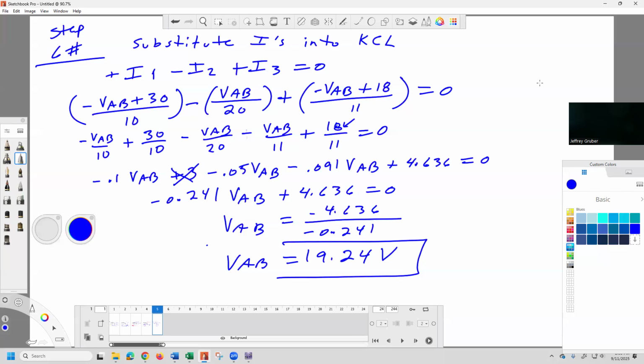So are you following? I'm trying to figure out how the two junctions, they have something between them to be two nodes, separate nodes. Yeah, because look at, if I put a meter here and measure, and then I put a meter here and measure, if there's a resistor there, those voltages will be different. If there's no resistor there, I can move my meter here, here, here, here, here, and I can move this here, here, here, here. It doesn't matter because it's a copper wire, right? I'm measuring the same voltage.